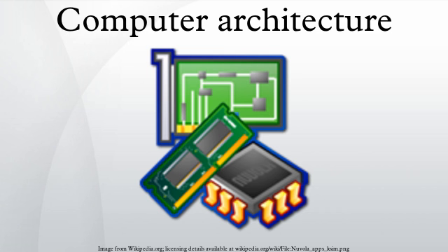Design validation tests the computer as a whole to see if it works in all situations and all timings. Once implementation starts, the first design validations are simulations using logic emulators. However, this is usually too slow to run realistic programs. So, after making corrections, prototypes are constructed using field programmable gate arrays. Many hobby projects stop at this stage. The final step is to test prototype integrated circuits. Integrated circuits may require several redesigns to fix problems. For CPUs, the entire implementation process is often called CPU design.